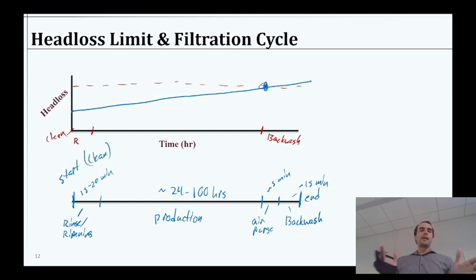So when we get to the math of it, it's really just doing some analysis of how many filters do we need? Given how efficient they are, how much time do we produce versus backwash, and what kind of loading rates and all that. It's just going to come down to that. So it's pretty simple, but it's a pretty big deal for most water treatment plants, especially surface water. Almost always have granular media because, again, it's pretty cheap, right? It's mostly gravity doing the work. Obviously, we pump the water, and then it's a reusable media, and it works pretty well. So it's very common,